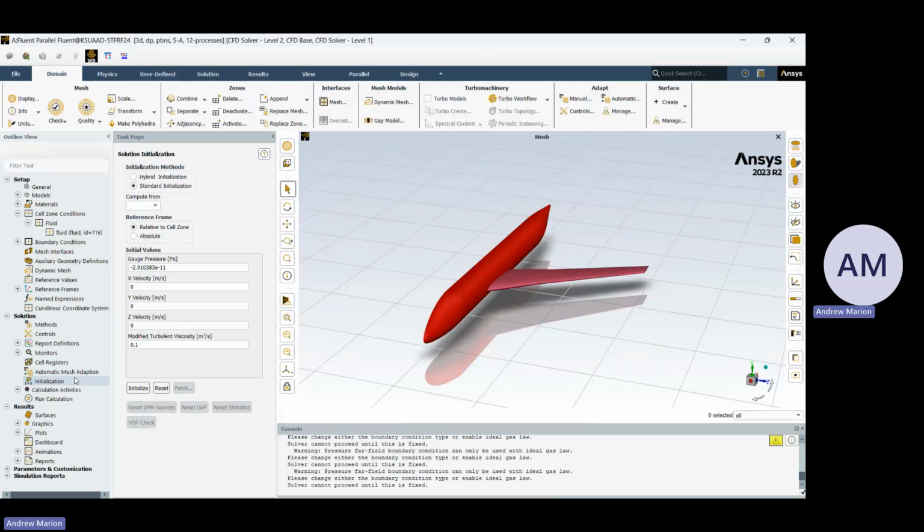Sometimes the continuity is real stubborn to get to converge. It really does not like to converge. So in extreme situations where you can get all the velocities to converge, but no matter what you do the simulation just will not converge the continuity, there you can set it to just ignore that criteria, because if you don't, it'll keep calculating forever until it gets it to converge. You don't want that. But for our purposes, it should be fine.